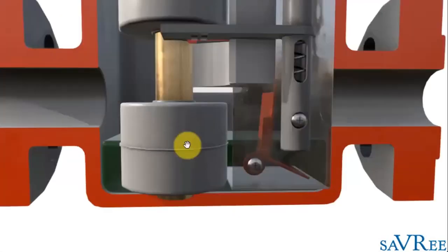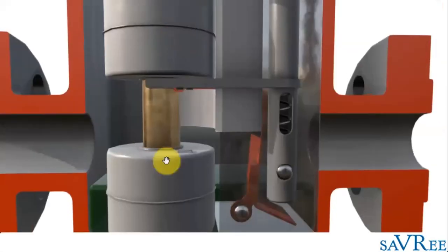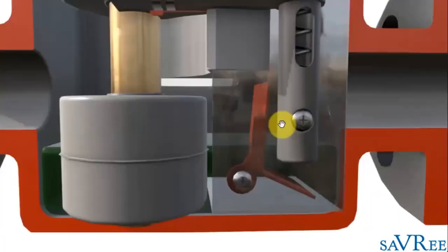Remember, the baffle plate pushing the lower float down was one shutdown, and now we've got two floats dropping together, the top and the bottom. That's another shutdown. So this is a shutdown scenario, and it means we've got low insulating liquid in the transformer. If that happens, then we have to take action immediately and find out what's going on.